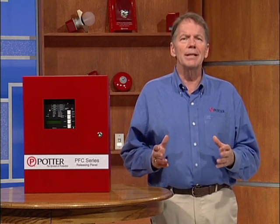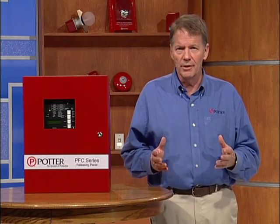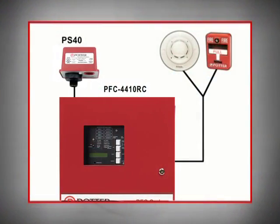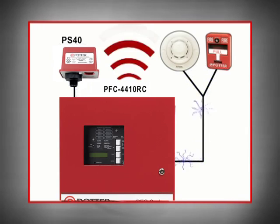In order for a double interlock system to discharge water, two independent events must occur. First, the piping must lose air pressure because the sprinkler opens. Then an initiating device, such as a smoke or heat detector or pull station, must be in alarm. These devices are connected to two separate zones in the releasing control panel.